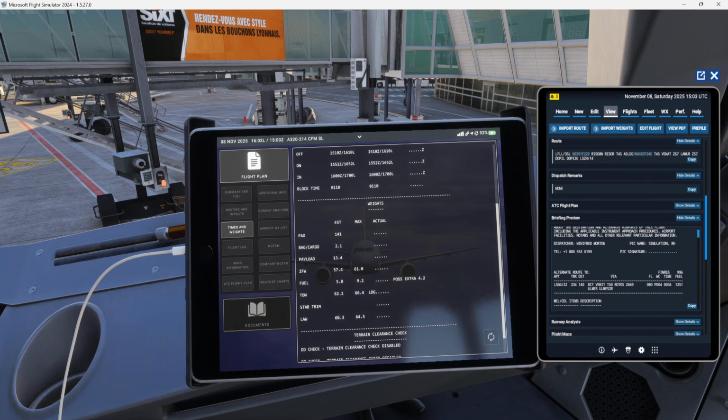Once you have the takeoff, well, let's go back a little bit. The dry operating mass, I'm going to say it again: it is the basic empty mass of the aircraft plus crew and standard equipment. If you add the takeoff fuel, you get the operating mass.